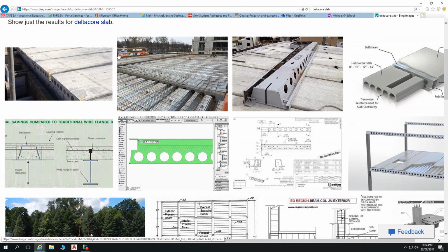But once again, it's another use of concrete, but where we've got pre-formed slabs, so slabs that are formed in a factory that have holes, cores, all the way through, where the concrete is not needed. So concrete is needed at the top and the bottom to help against compression, deflection, etc. But that strength is not needed in here. So you save on concrete and you save on weight, and those floor slabs can be craned in. You can also do precast, so other forms of precast slabs as well.